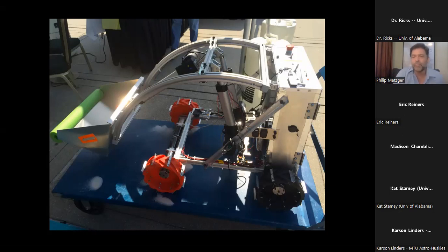Also, I didn't mention, but ground clearance is another important one. Some vehicles get stuck because they dig in and maybe they could have gotten out, but the chassis hits the ground before they have a chance to finish digging their way out. So having more ground clearance gives you more margin to pull out of a hole. Also, if you accidentally drive over a rock, having a higher ground clearance can help you avoid one of these initiating events where you bounce on the rock and then the wheels slip a little bit and then it induces a runaway series of events. So ground clearance was also important.